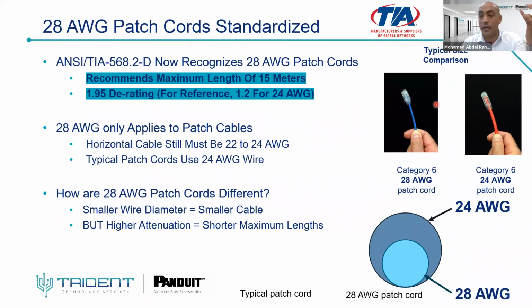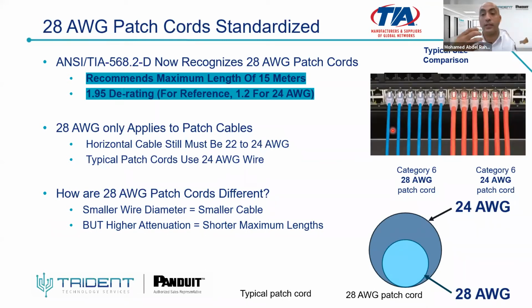You can compare the different patch cords: the 24 AWG, which is the traditional patch cord available in the market, and the 28 AWG patch cord, which is innovative and also from Panduit. After 7 years, as we said, we launched this patch cord in 2011, and in 2018 it was approved and recognized by the standard. Using this cable can give you better port visibility and easier cable management. You can have space for your finger to connect and disconnect the patch cord.